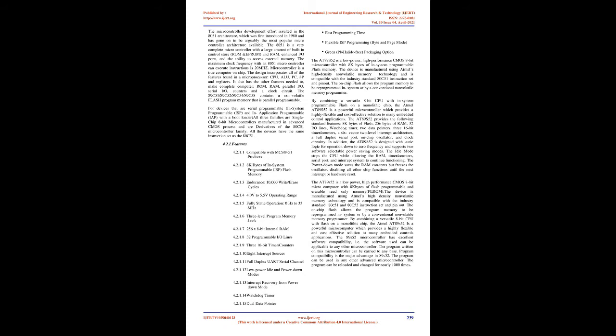The design incorporates all of the features found in a microprocessor: CPU, ALU, PC, SP, and registers. It also has the other features needed to make a complete computer: ROM, RAM, parallel I/O, serial I/O, counters and a clock circuit. The 89C51/89C52/89C54/89C58 contains a non-volatile flash program memory that is parallel programmable.